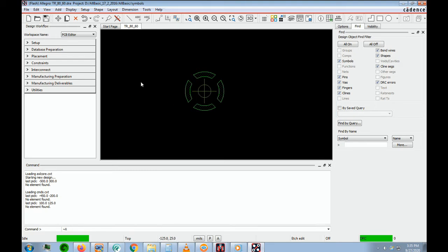This is all going to be copper, and the pad goes through this big hunk of copper. If you don't have these spokes, the copper will soak up all the heat that goes into this pad, and the pad will not solder properly. So thermal reliefs are very important.